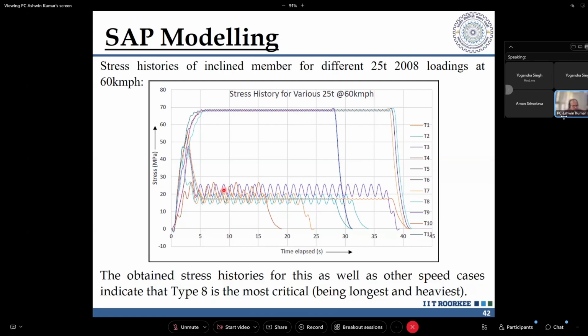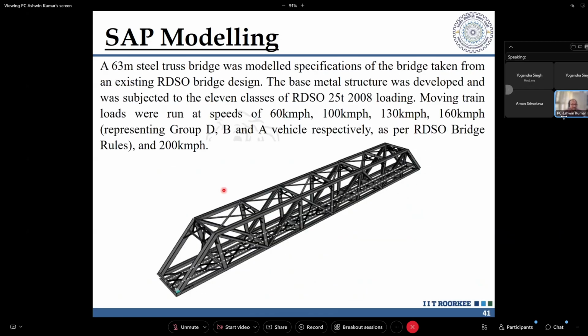So what you do is run the loads designated for fatigue analysis, find out the variation in the load that is coming, and find out the stress range that is developed. If you can identify from the bridge which members, let's say you have inclined members, where as per truss analysis you get axial load variation in that particular member. But the question is, out of all the diagonals, which diagonal is more critical, or where is the maximum stress range going to happen?